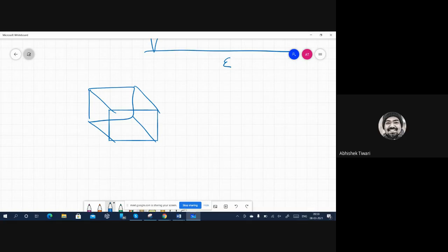So let us look at this RVE, and we are defining damage. Damage has increased, so it has started. That means it is greater than 0, right? And then at which point do you think it will fail? So let me answer it for you. You don't have to wait until damage reaches 1.